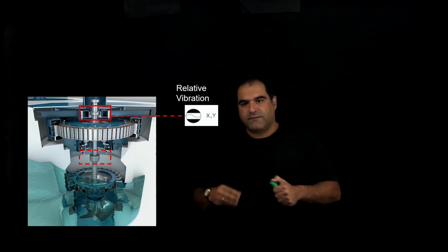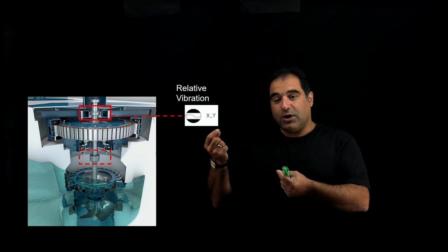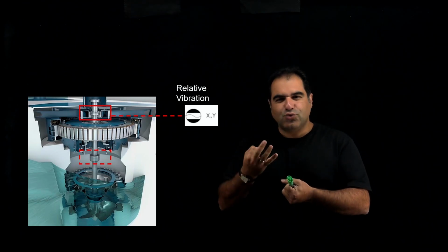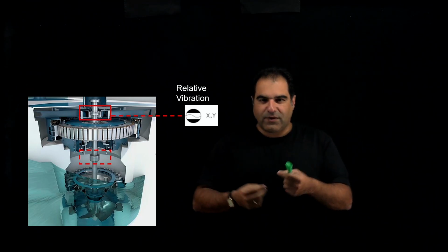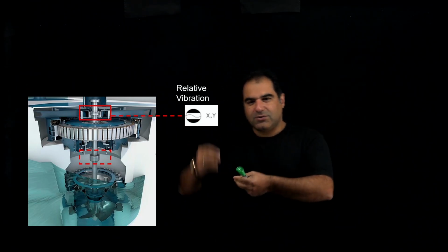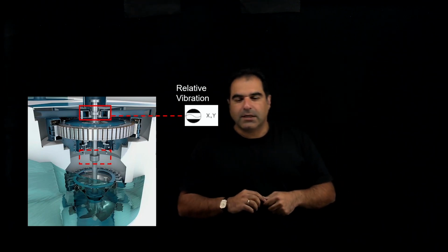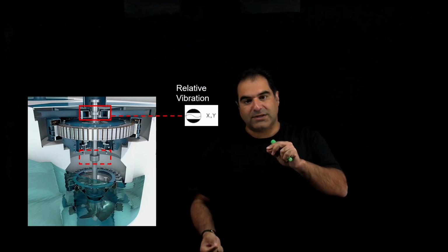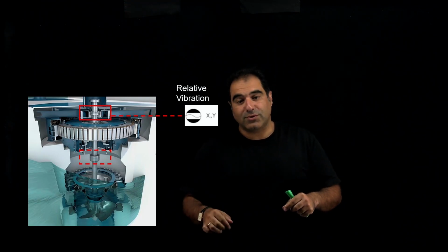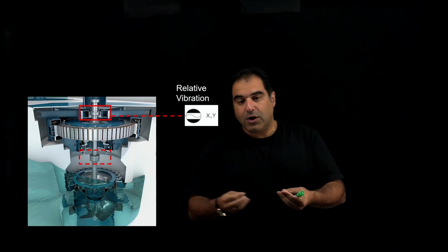This is the schematic of the hydro turbine, and usually people are able to measure the vibration at 2 or 3 locations. For example, I showed 2 of them, the bearing locations. Usually, they measure the vibration in the X and Y directions. The shaft of the hydro turbine is very long, almost 10 meters, so you are measuring the vibration very sparsely. You have sparse sensors: you only measure the vibration at 2 or 3 locations, in X, or Y, or both.